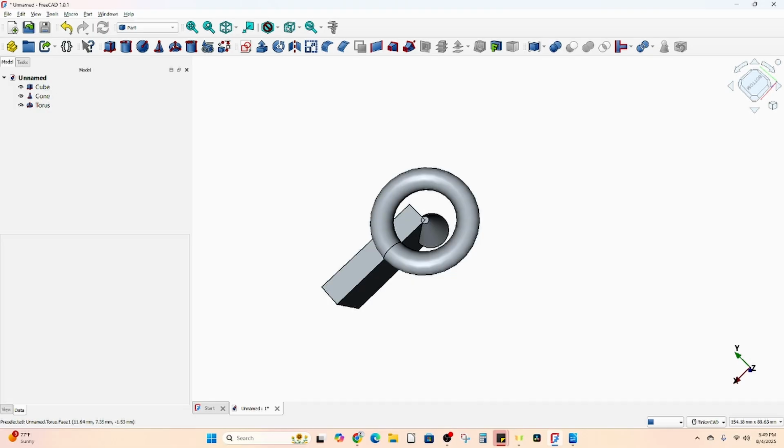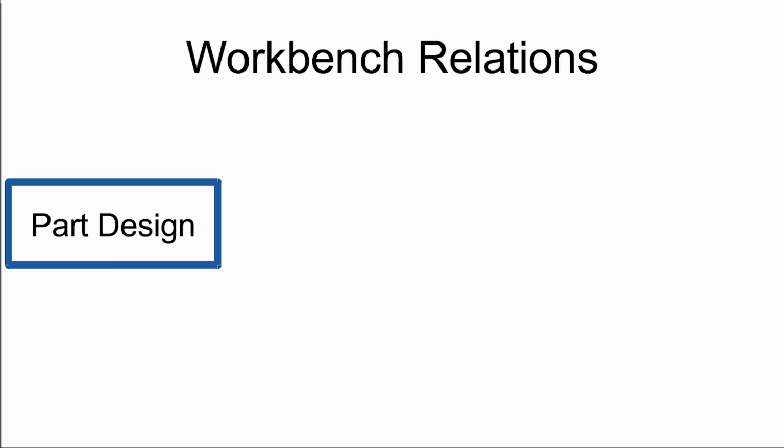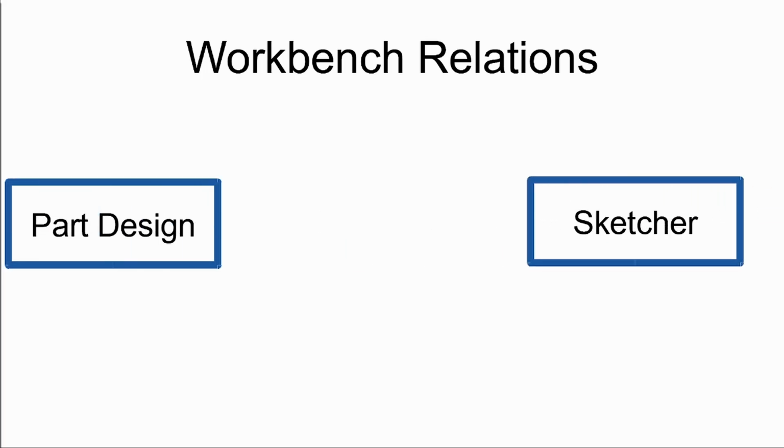We went over the workbenches. Oh, okay. Let me show you something here real quick. Okay, here we go. After that long explanation, now I'm gonna PowerPoint you to death here. All right, here we go. So we got the part design workbench, which I'm gonna show you how to use before we end this video. And then you got the sketcher. Those are the two that you jump back and forth between while you're designing your part.